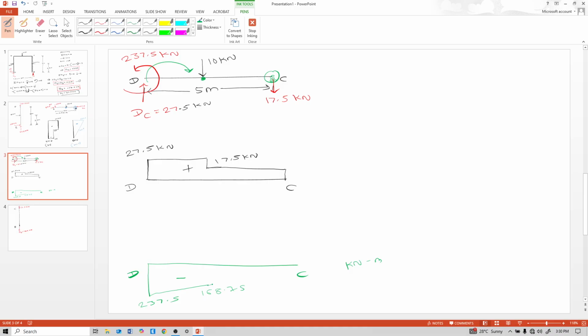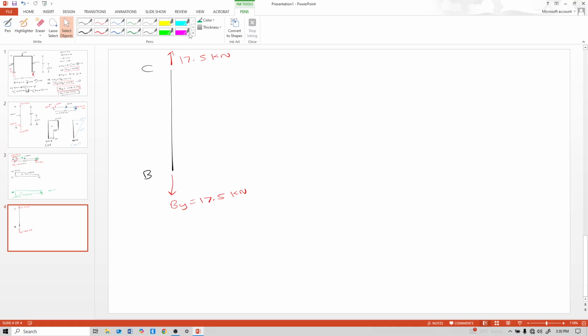So that means here moment takes similar, 125 anti-clockwise. So see, draw SFD here, shear force diagram for this CB beam. CB SFD, no SFD because no transverse load acting here.